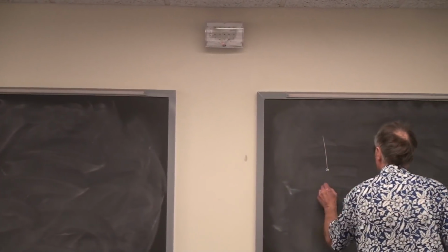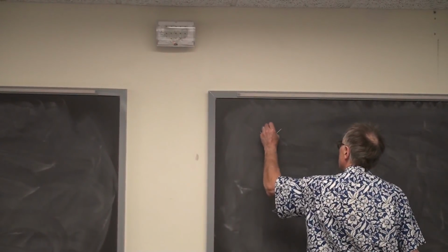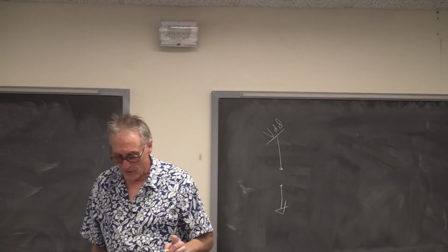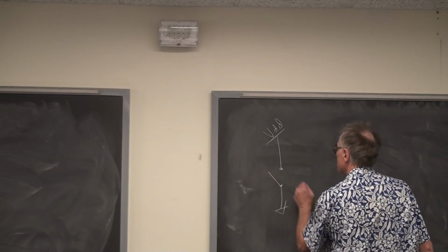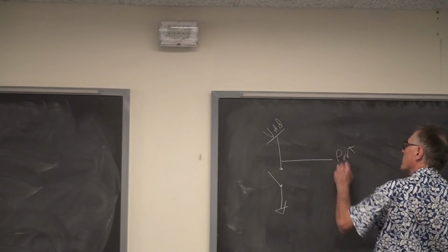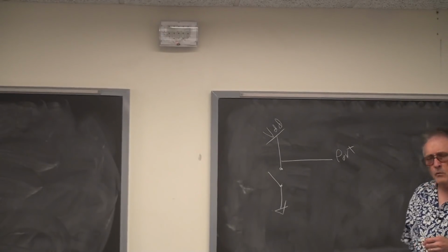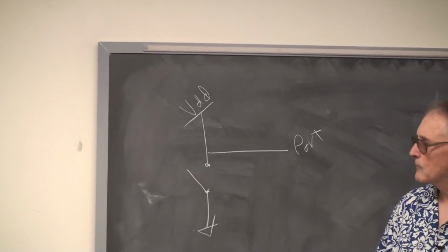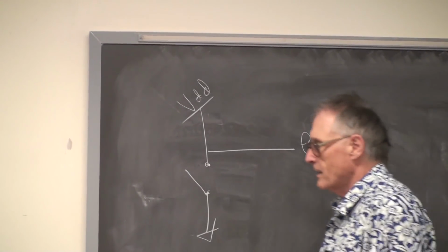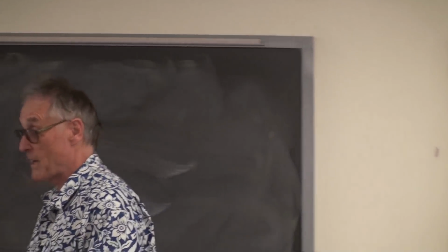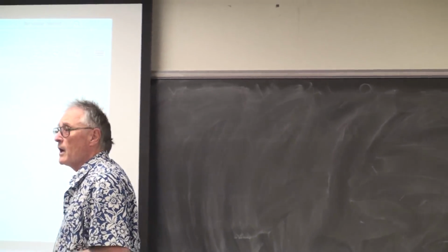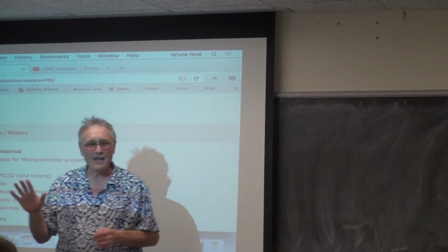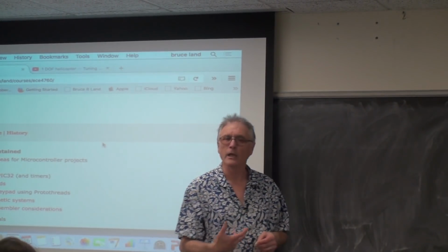Student will build this circuit, VDD. Make sure I get this beautiful thing right. They actually use a single pole, single throw switch and hook the port pin to here. And they'll say, it's really weird. When I push the button, the system crashes. And in the old days, when we had fused power supplies, you push the button, it blows the fuse. I had one student who blew 500 fuses one semester. That's an example of kind of not learning what's going on.